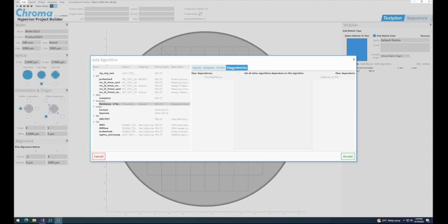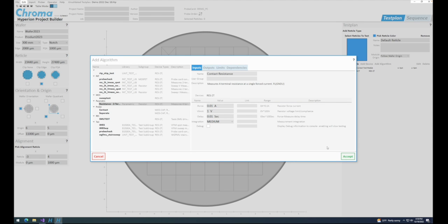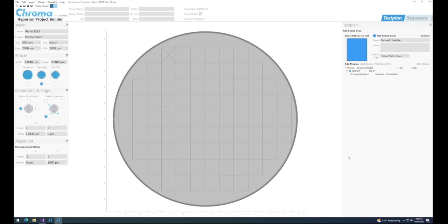Execution order. The execution order of a test plan will follow the order seen in the test plan tree from top to bottom for serial execution. When parallel execution is supported by hardware and enabled, we'll have implied timing that cannot be guaranteed. Sometimes this is fine, other times this should not be allowed. This is the scenario when the Dependencies tab comes into play.